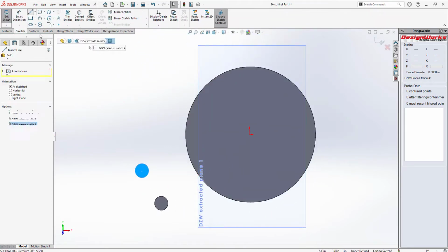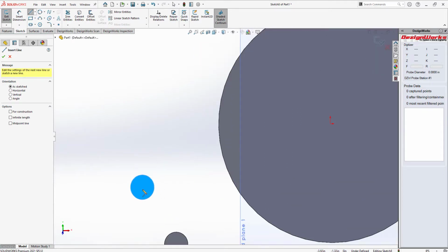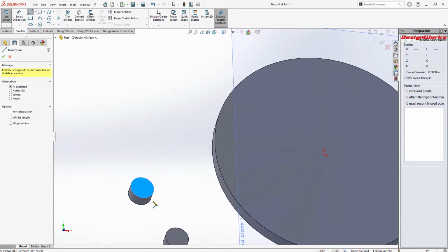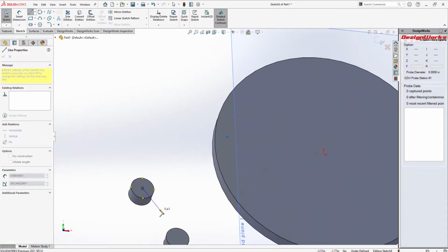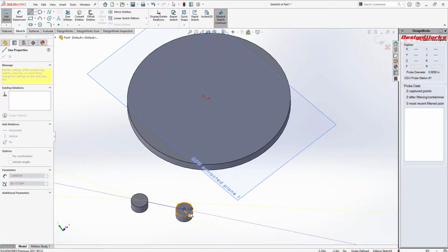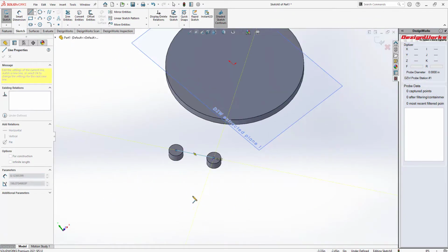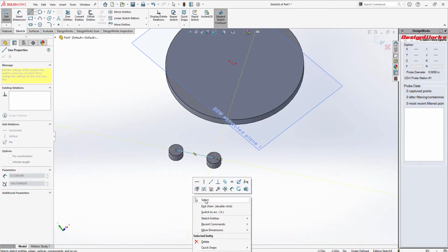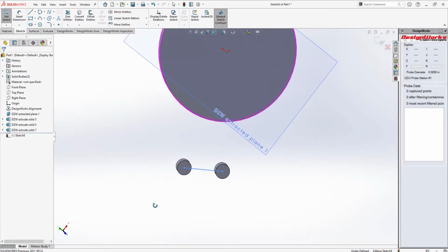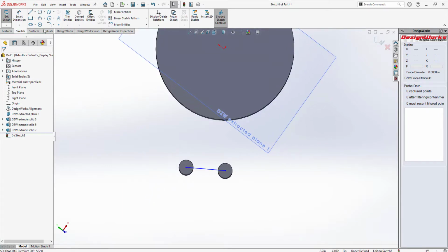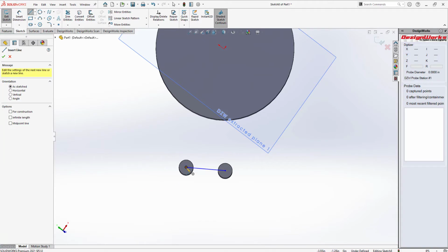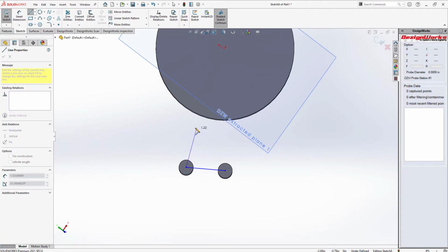We're simply going to draw a line, and it'll inference this. If you come up here, it'll inference. And if we go over here, notice it'll inference on the other cylinder. That's going to be our X. In this case, we want a Y that's perpendicular. We can simply use the SolidWorks line command again. So inference off that and rotate it up. It'll show us our 90 degree.